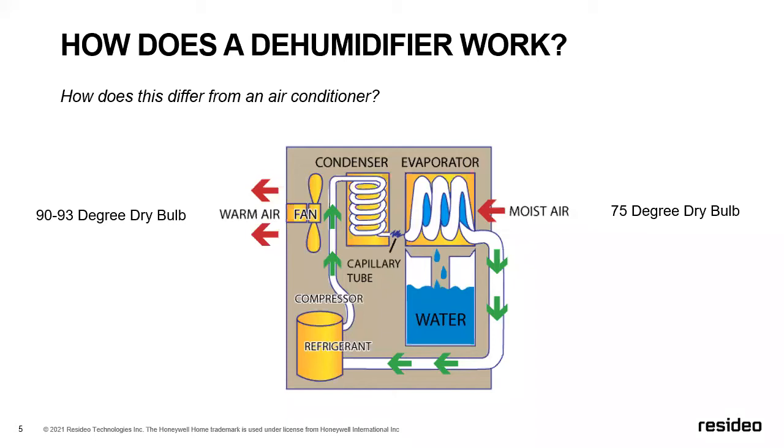We know our fan motor's working, and most likely the machine is effectively operating at what we would provide as a specification for that. So just a really simple slide that gives you the anatomy of what's inside and how that refrigeration circuit works. That will give those on the call who may question whether a dehumidifier is operating a simple check: take a measurement of inlet to outlet.